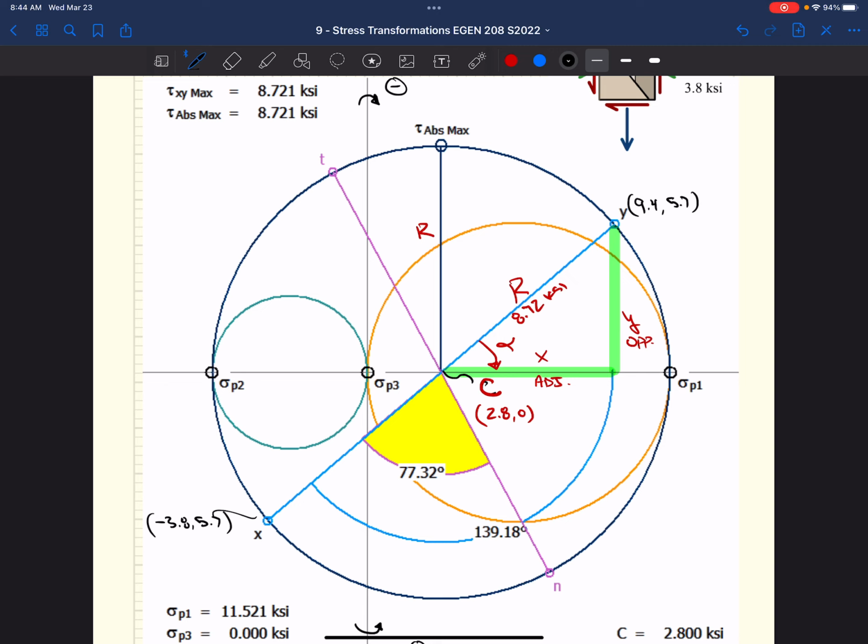It is really cool. And it goes to show you that depending on the material, chalk is very brittle. It's not very good in tension, okay? It can handle the shear stresses, obviously, but it can't handle the fact that you're trying to actually pull it apart. It has tension in it. The tension that's in it is at a different orientation, and you're not even applying a tension force on it, right? If you were to pull the chalk apart, put a tension force on it, you know it's going to break in half, perpendicular.